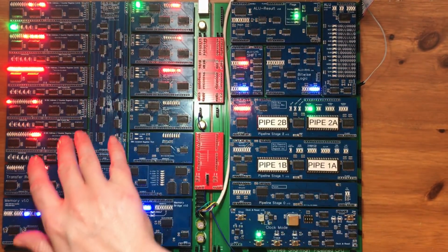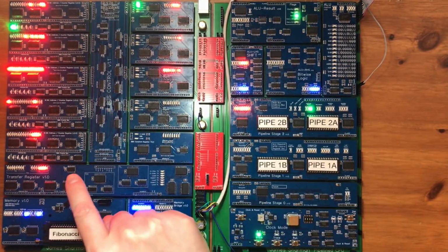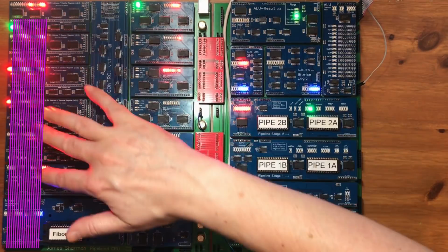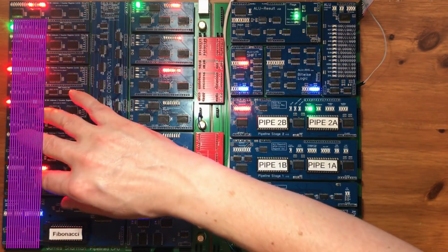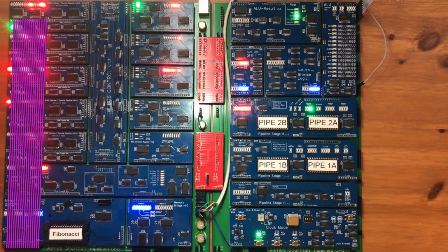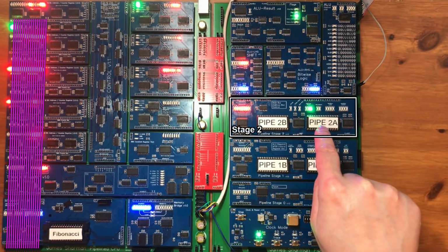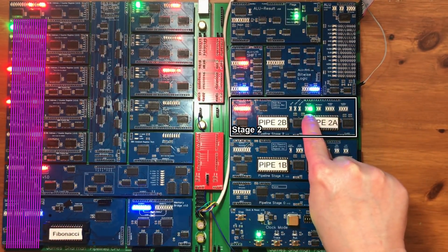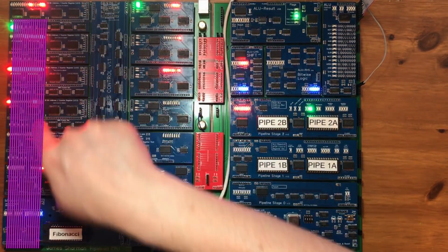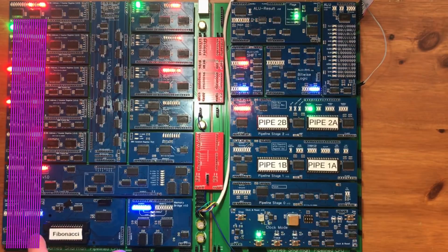And over on the left-hand side, we have two 16-bit buses. Firstly, we have the address bus, which any of the 16-bit registers can push their data out onto, but only one at a time, obviously. That's controlled by pipeline stage 2 when the address select control outputs. And that's just a one-based index into these registers to let them know which one is commanding the address bus.